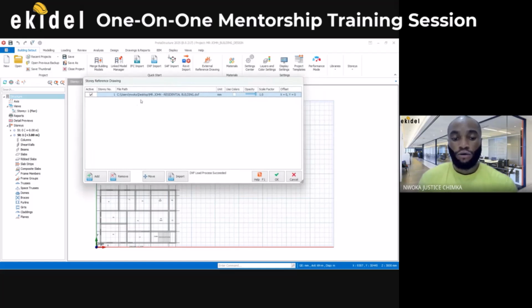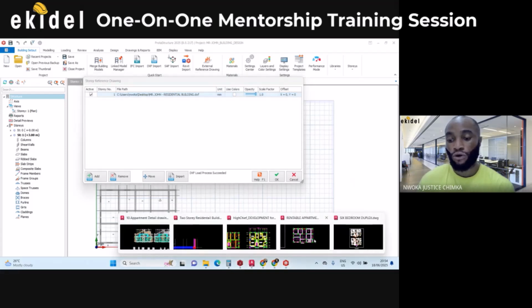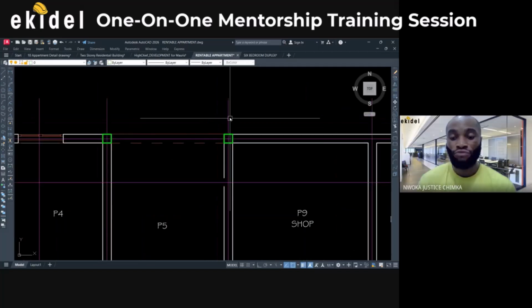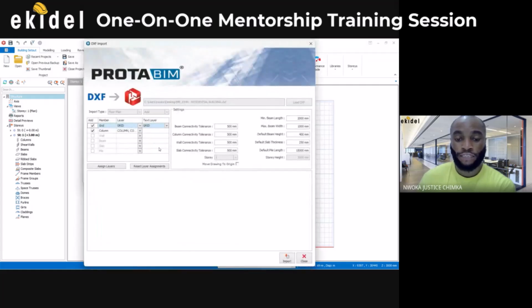Once you have done that, the next thing to do is to import the grid lines and the column members that we set when we were doing our framing. We need to import these columns as column members and these grid lines as our grid axis. So come and say import. You can see there, import DSF. I'll click on this place, and then they will ask me a question: import grid and import column. I'll say yes to just those two, and then click on import here.